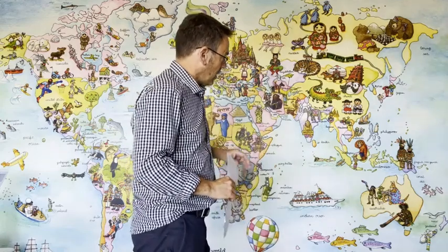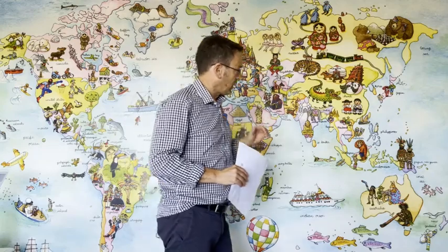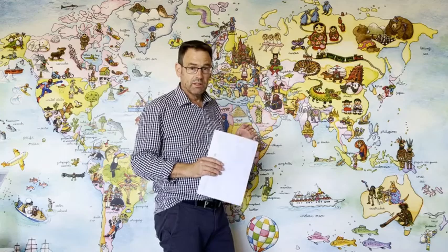country. If you go to even smaller countries like, let's say, Singapore and Hong Kong, then they've got the luxury of adopting an even more customised grid to that specific location, and therefore scale factor can be almost negligible for most applications. Now, if I relate this back to fruit and vegetable, what this means is, depending on where you are in the world, over a 200 metre baseline, your distortion could be as small as a pea or as big as a carrot. So you do have to pay attention to it.